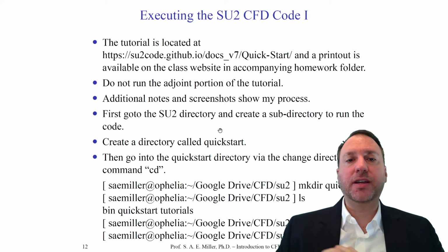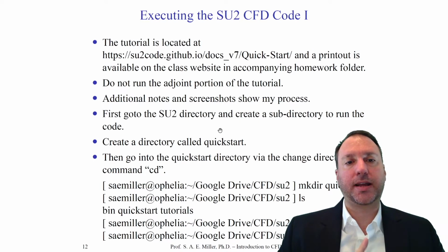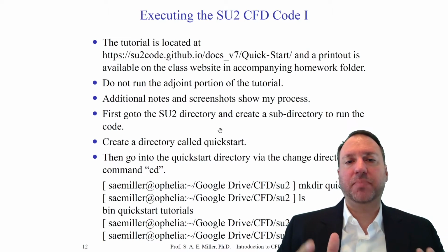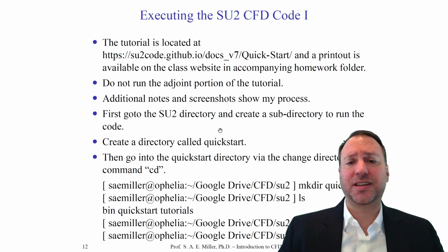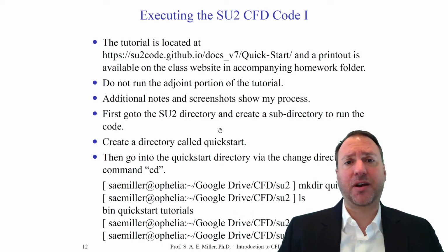And for every case or every simulation we run, we will create a new subdirectory in SU2. We will never reuse a subdirectory. Always create a new subdirectory for every case you're studying. This way, they won't be mixed up. Some students make the big mistake of running all their CFD simulations, like 5 or 6 simulations, in the same directory. And they, of course, overwrite files and it gets all mixed up and they're confused.